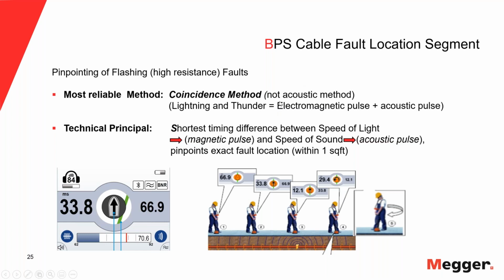So it basically measures the time for the sound to get to you, because the thunder, or in our case, when we fault locate, the electromagnetic pulse from the flashover will travel at the speed of light. We cannot even measure this. But we can measure the time it takes for the sound to get to us. And so you can say this type of pinpointer is like a stopwatch.